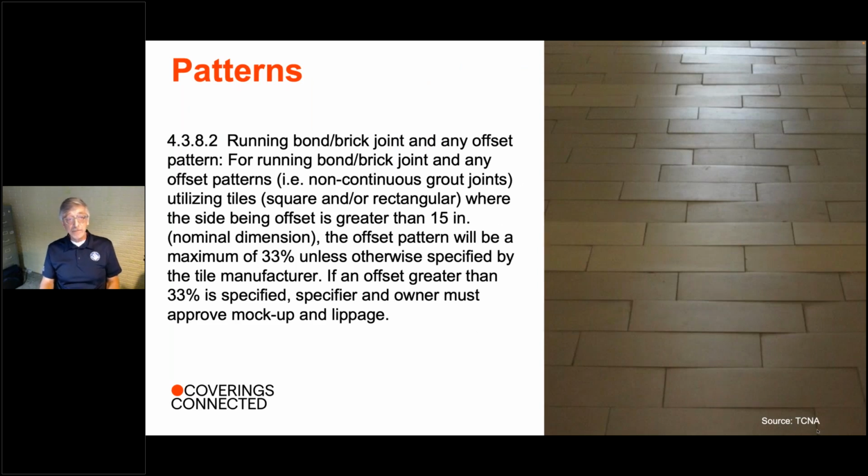I said patterns matter. The 33% offset, have you ever heard of that rule? Well, it comes out of ANSI A108. And what it does is for tiles that have some warpage, we divvy that up. We spread it out throughout the tile installation so that the high spots aren't next to the low spots in tiles 15 inches or longer. And that means that we're going to have fewer chances for shadowing when the light is cast across that tile.